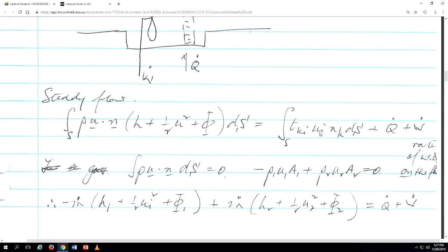But it's also true that on normal surfaces to the flow, this tau_kn n_k will be, for example, tau_xx in the x direction, or minus tau_xx. And tau_xx is 2 mu du/dx, so if there's no gradient in x for the streamwise velocity, it's identically zero, and it does no work.